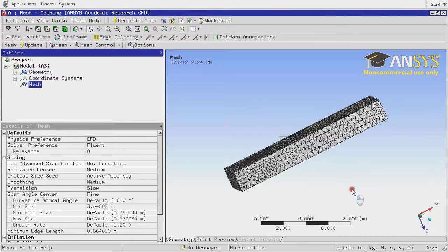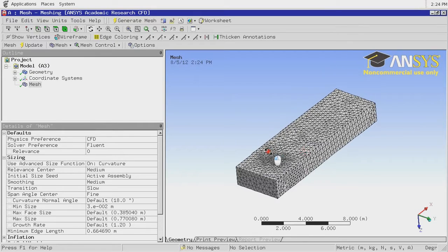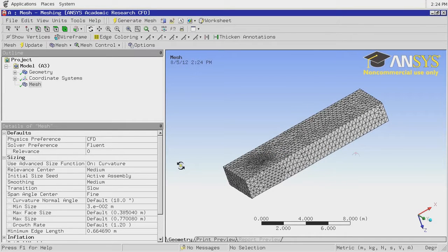Okay, I want just to tell you about something. I'm not going to work on it over here because it requires a long time. Don't think that CFD simulation takes 10 to 20 minutes to just finish it. It requires a long work, and it requires a lot of concentration. The thing is that on the wall of the airfoil, the mesh should be very refined, and this requires a lot of cells over there in a smaller size.